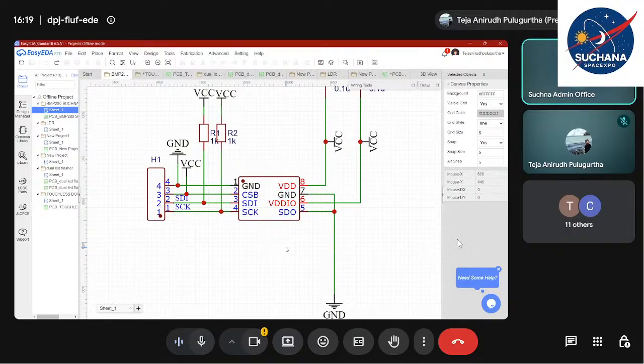So you have no option, right? Even though you set it to 0x77 or 0x76, it will cause an I2C address conflict, because we already have another BMP280 sensor module with the same address, so you cannot specify the same address for them.